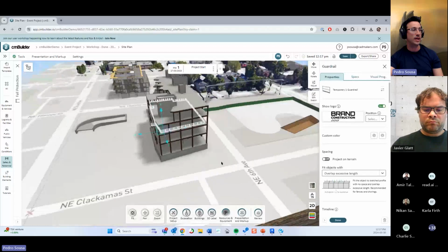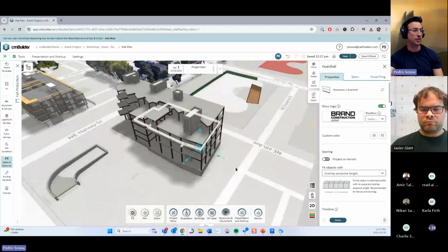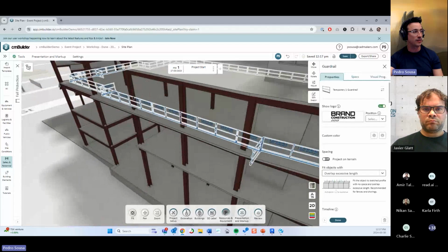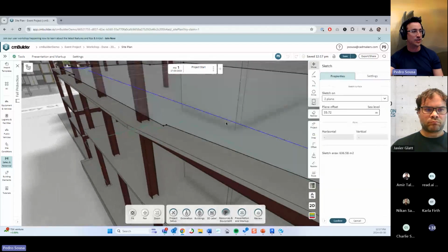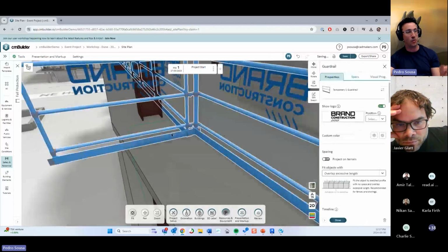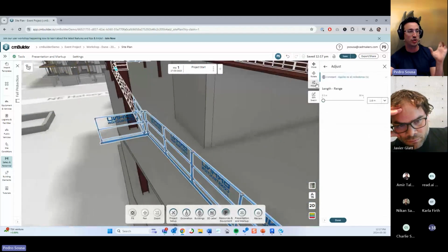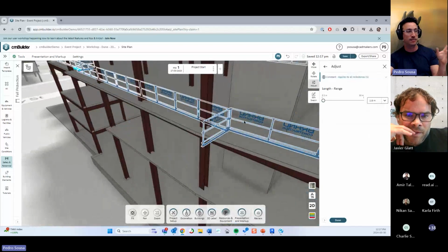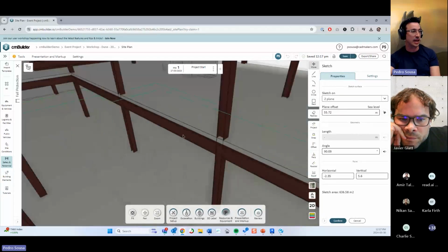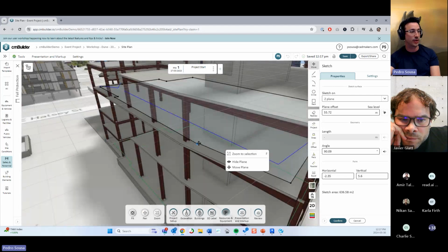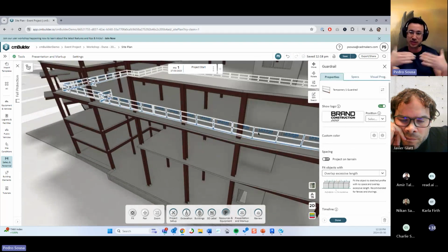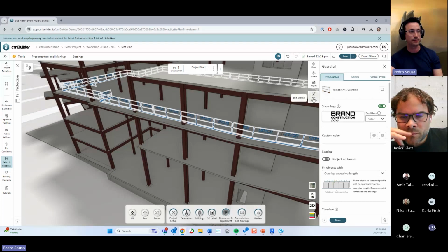Okay. So when I hit OK, now I have my edge protection going on over there. You see that this edge protection created some weird placement of these panels over here because in my sketch I have a very small segment of this line. So the software will try to place that panel, but all the panel shapes and widths are standardized. So in a situation like this, what I would do is basically just delete this line in the middle over here. Oh, sorry, delete the point, and then it will reconnect with the other point, and that's it. You just need to adjust your sketch so there are not super small segments of the line. Cool.